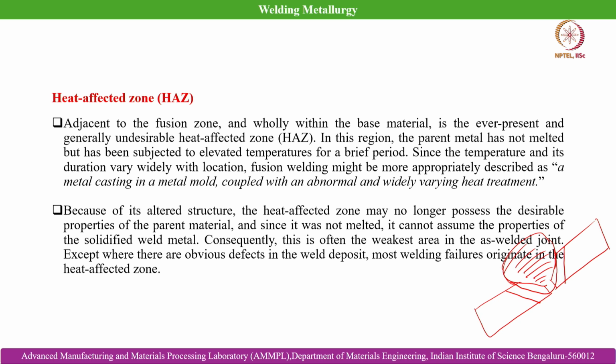So, that is why normally the strength of this HAZ, the heat affected zone, decreases significantly, and it becomes the weakest link or weakest region of the weld joint formed between the adjoining plates, and thereby often it serves as the failure initiation site. I mean, where failure initiates in case of a weld joint.